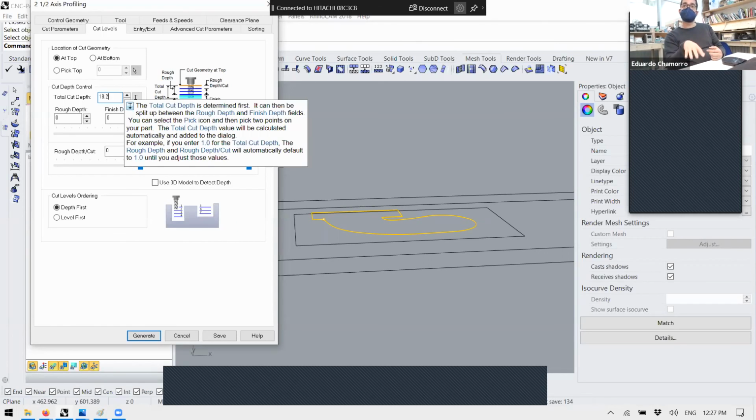First, a cleaner surface on the top, and exactly this. In this case, the wood is a good wood. The layers are thin. It's easy to chip the edges out, and it will get a worse result on the back. But the back is pressed against the bed of the machine, so it's not chipping that much. In general, for plywoods, if they work really well, we don't need to fix as strongly as with the up cutter, because it's not tending to move the material down.